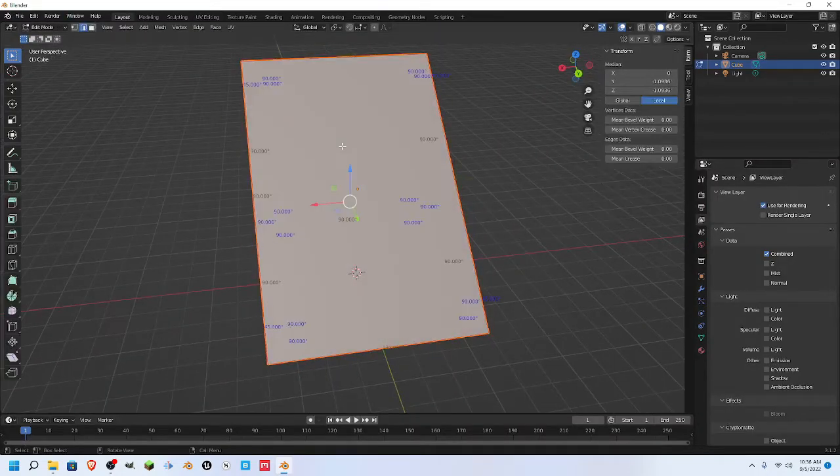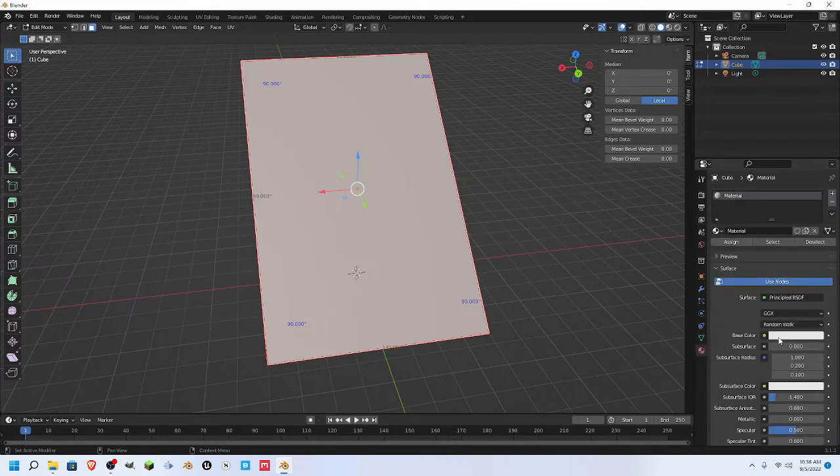Next up, we will go back into edit mode. We are on faces, and we're going to put some materials on this. We're going to go to our material properties tab. It is located on the side here, this little round bar with the ball with the checkerboard. Click on that. This first material we will call shingles, even though it will be changed later. S-H-I-N-G-L-E-S. Come on, Pitt, you can do this. Let's make it pink because we want this to be easily identifiable if we have not changed it.